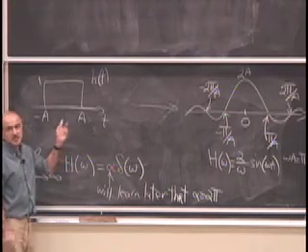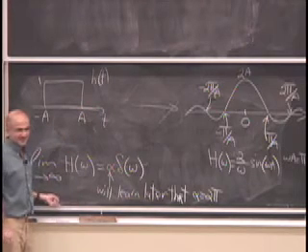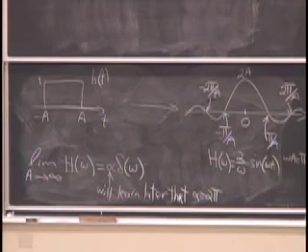By the way, if you don't believe me, try a sinc in the time domain and plug it into that integral and see if you get anywhere. You can actually see it by just replacing this omega with a t. Let's say I had a t here, and I had an h of t here. This sine oscillates between -1 and 1, so it's always on the order of 1. This t in the denominator decays on the order of 1 over t. And you know from calculus that things that decay according to 1 over t don't converge. So when you plug it into the frequency response expression, you're not going to get anywhere.